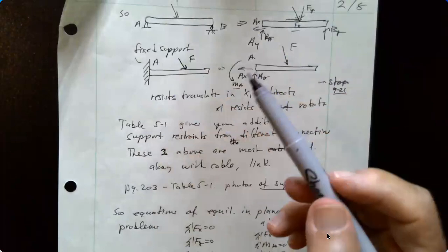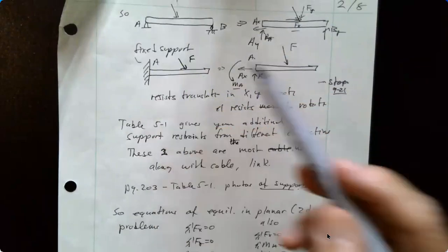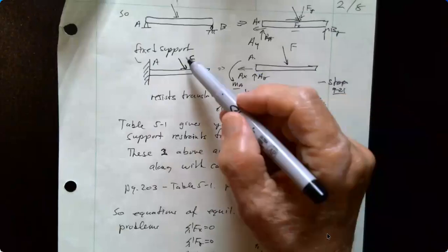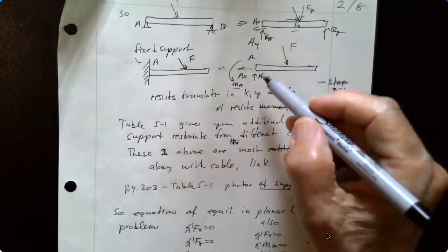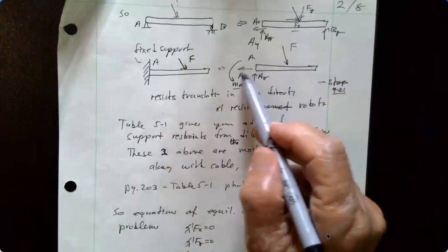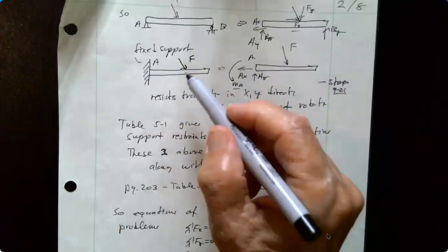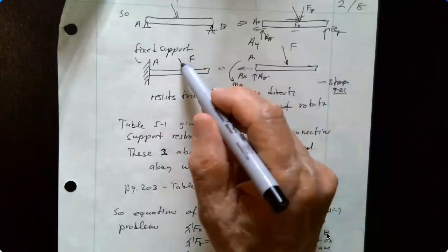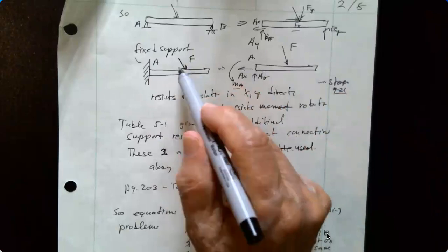And again, we apply a force at an angle out here. The support is labeled A. And we know this is going to provide a y component and an x component, so we're going to have a y reaction and an x reaction, okay, which I have here. Also, we recognize that this force would cause a rotation in this cantilever in this direction, okay, in the clockwise direction.